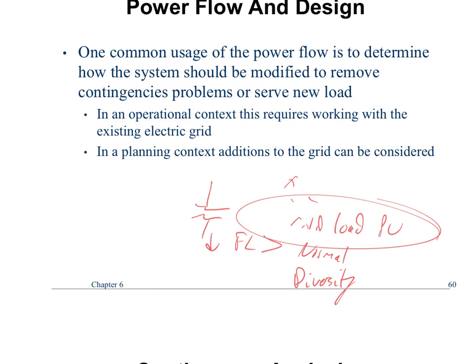That's inrush, that's different. This is maintained. Inrush, you just deal with it. You're going to have some low voltage, but you can deal with that pretty well. Cold load pickup goes away once everybody's diversity starts to come back into normal, you actually have diversity. So when your current is sky high and then it drops below your normal full load, then it's no longer a cold load condition, right? Now we're starting to have diversity.